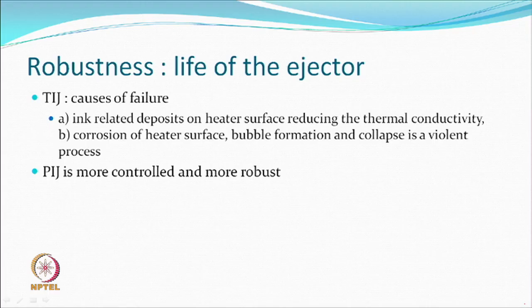Why will it fail? It can fail for various reasons: maybe filtering is not good, maybe something else has come up, or maybe the ink and head combinations are not good. Maybe we had talked about it before, that thermal inkjet can fail because there is a heater, and for various reasons there may be deposits on the heater surface.